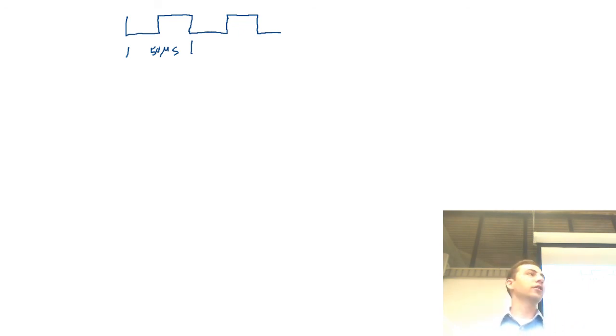The first gotcha in this kind of problem is that 50 microseconds has nothing to do with this problem. The thing that matters is 25 microseconds, because we're doing waveform generation, so an event happens twice a cycle. It happens here, and it happens here. There's my cycle. It happens twice a cycle. So we've got to do some math.